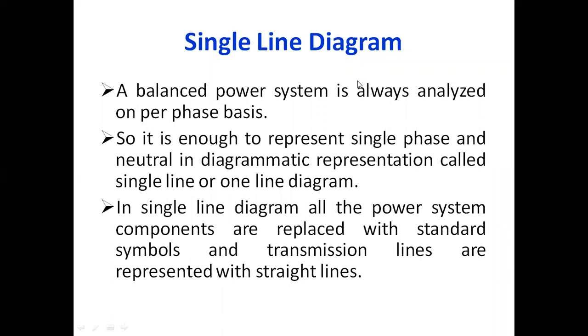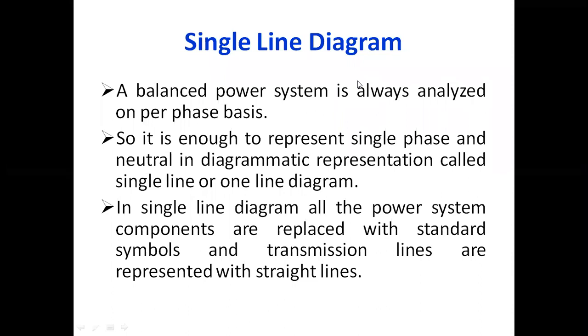Okay, so I'm not going to say that a single line diagram is not possible for an unbalanced power system. If you want, you can draw it, but the main thing we are going to learn is that we are using the single line diagram for making the analysis of balanced power systems. Once you obtain the voltage, current or power for the single line, you can extend that same analysis to the three phase system also. Just multiply it by 3.